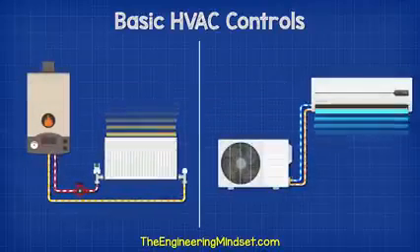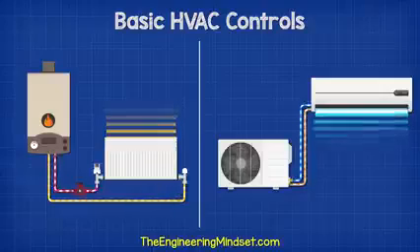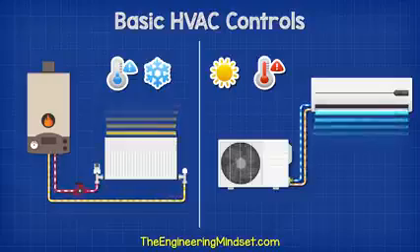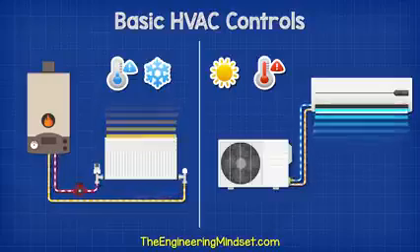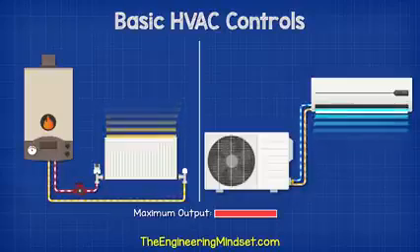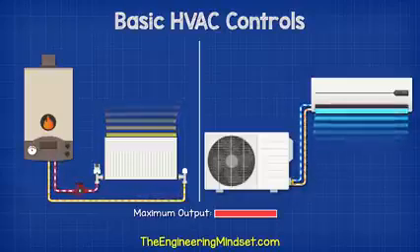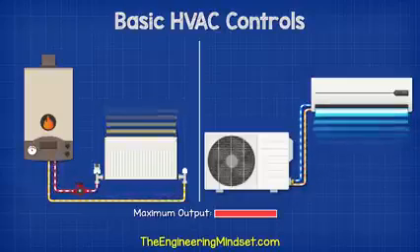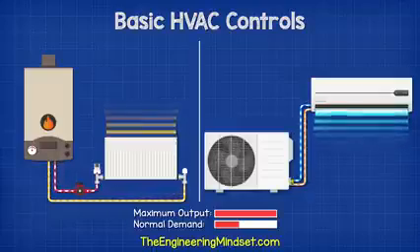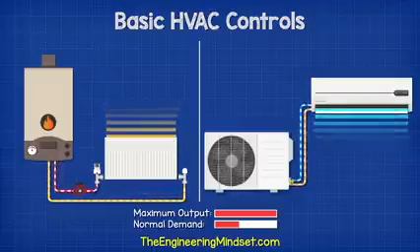We rely on our heating and cooling systems to function whenever needed, especially on the coldest and hottest days of the year when the system must operate at full capacity. To achieve this, the systems are typically oversized, so that they can handle the worst-case weather scenario. However, most of the time the system will operate well below this point at part load conditions.